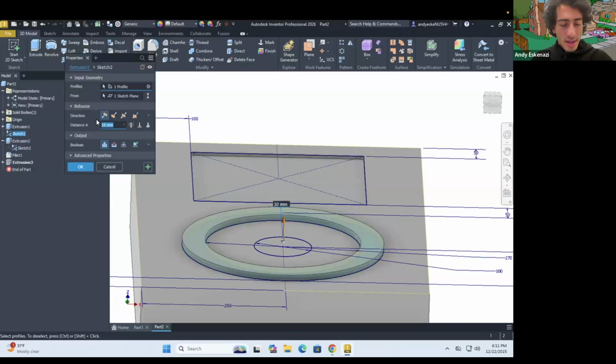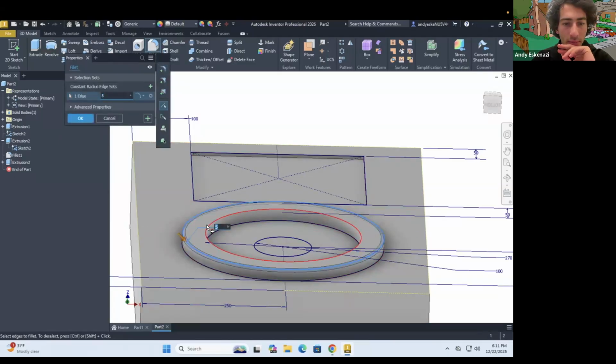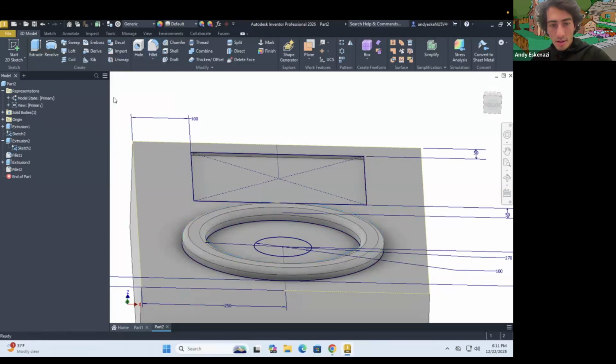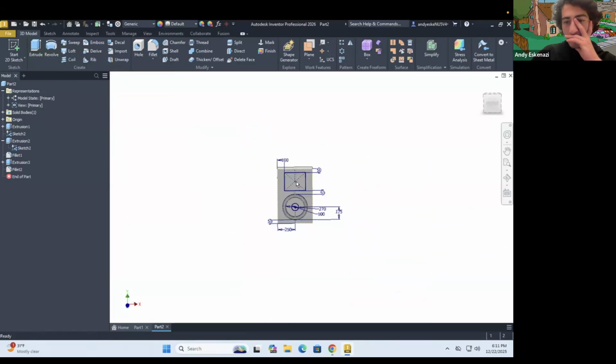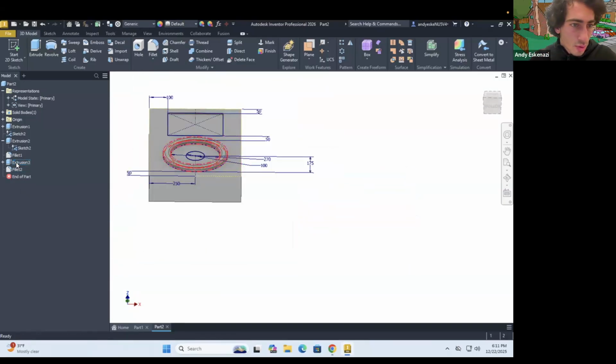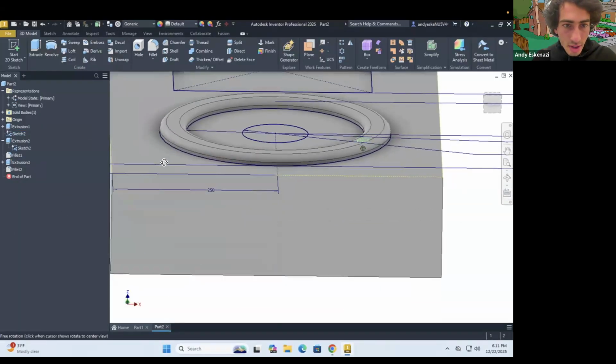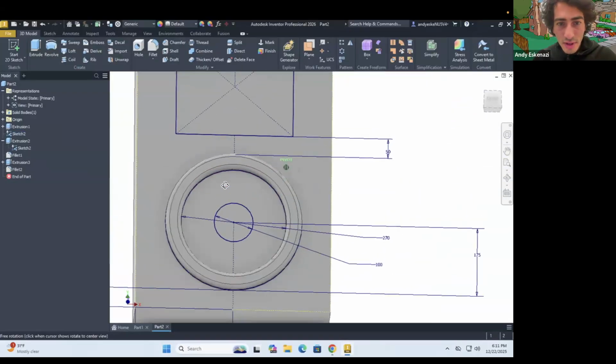We'll make that 20. Because now we go here to fillet. We say, boom. We want that to be 10. Just like that. And actually, maybe that is too much. So, feature, I'll make that 15. Here we go. Yes, I'm more satisfied with that.